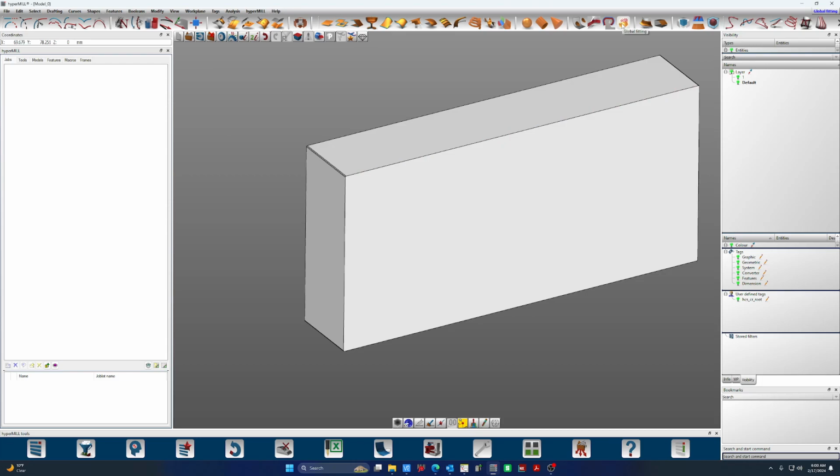And global fitting. Global fitting is a pretty neat tool where we have a bunch of surfaces that have some sort of, I want to say, semi-relevant tangency, but maybe vectors that are off in all sorts of different directions. We find this really commonly in orthopedics, where they've done 3D scans of human bones and actually made bone plates based off those scans.